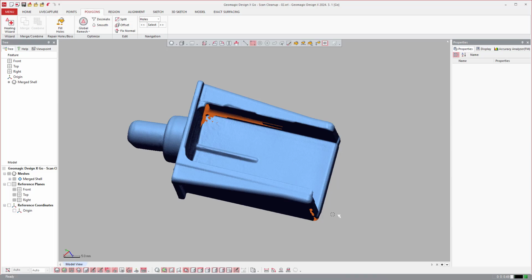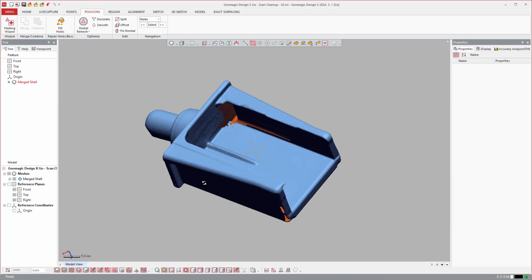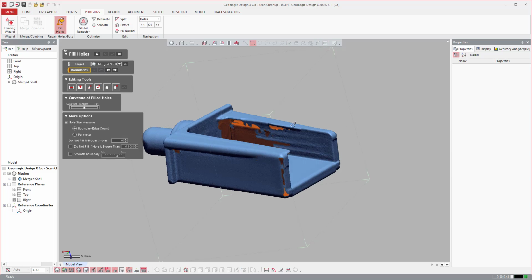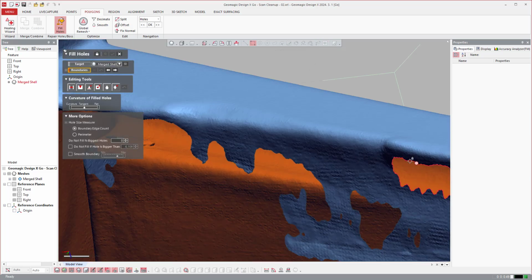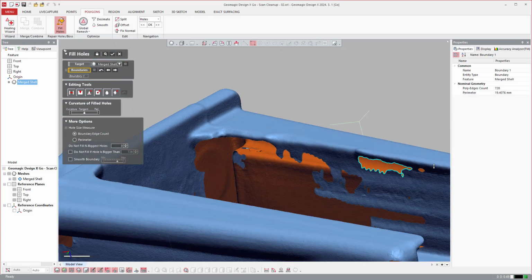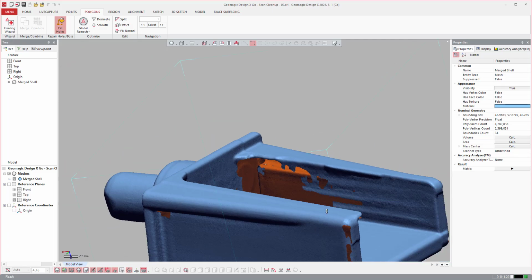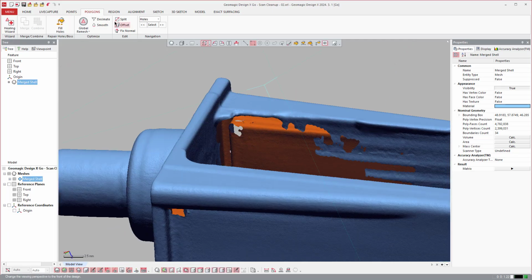Now you'll find everything just moved a little faster, and with the hole fill tool you don't have to select what mesh you want. It just auto selects it. So you can do things like this and hit OK. You see that, and it just automatically selects those. Now, for hole fill, I'll just cover a few different things here.